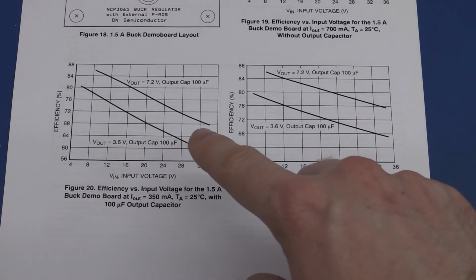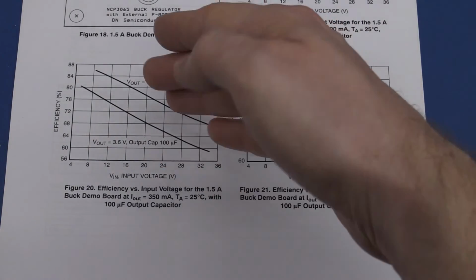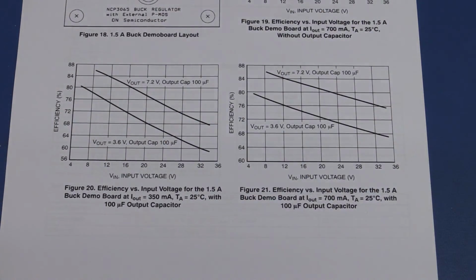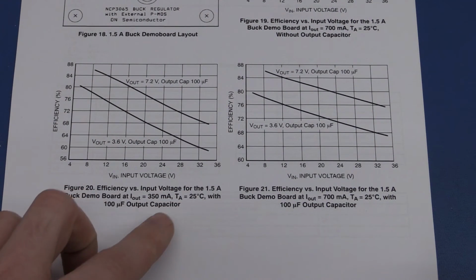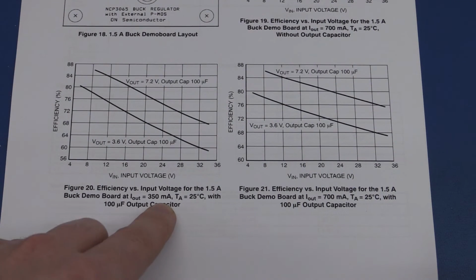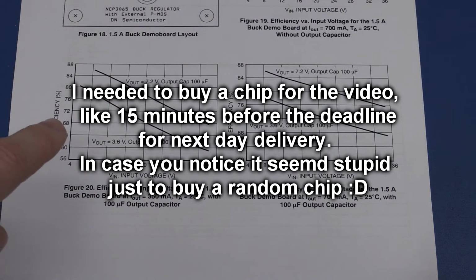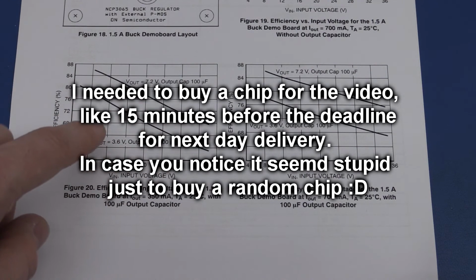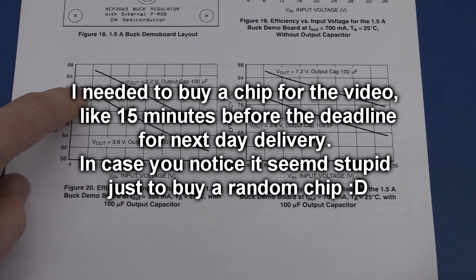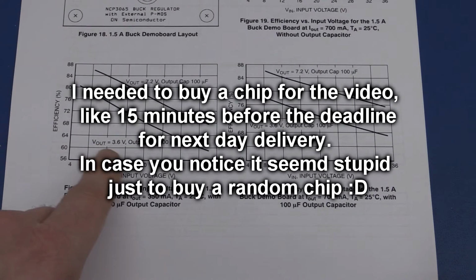I'm using a much lower current, around 23 milliamps I think, so my efficiency might be very bad. I don't really know that yet. For the lamps that I'm making, I'll probably run it at around 200 milliamps, so also even less than this. When I said the chip doesn't seem to be as good as I hoped, I'm referring to these graphs here. It's pretty good here at around 80–85%, but as the input voltage goes up, you really lose the efficiency.